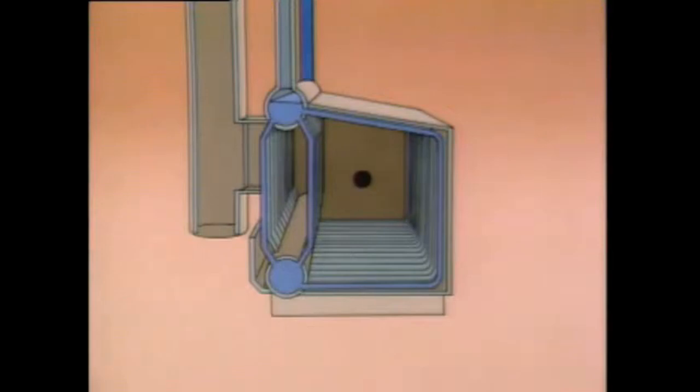Generally speaking, water tube boilers use tubes to route water and steam through the boiler. The combustion gases flow past the outside surfaces of the tubes. Let's examine this principle in more detail. Water tube boilers may vary in design, but most of them operate in basically the same way. This particular boiler consists of a series of water tubes and 2 drums.